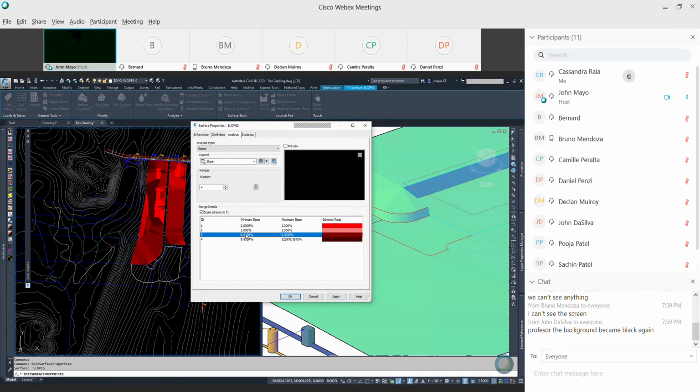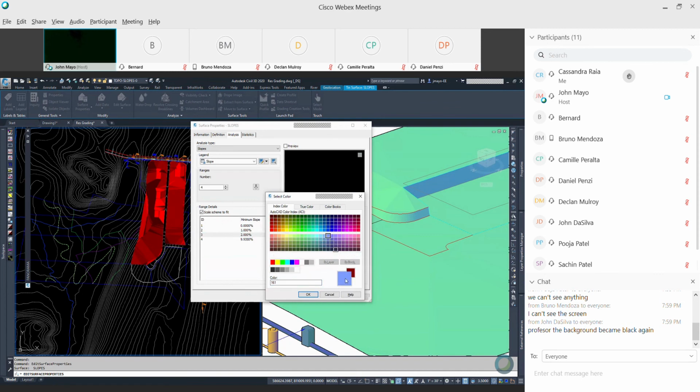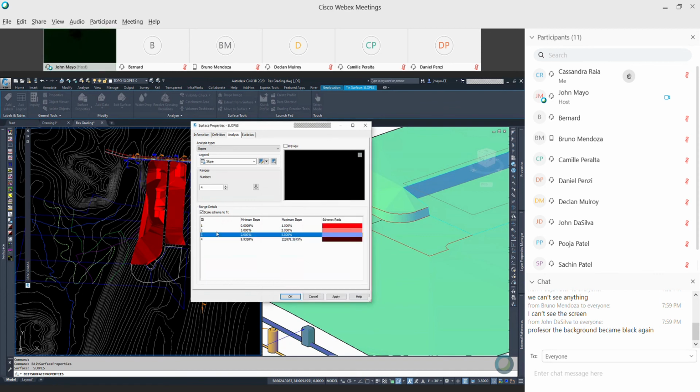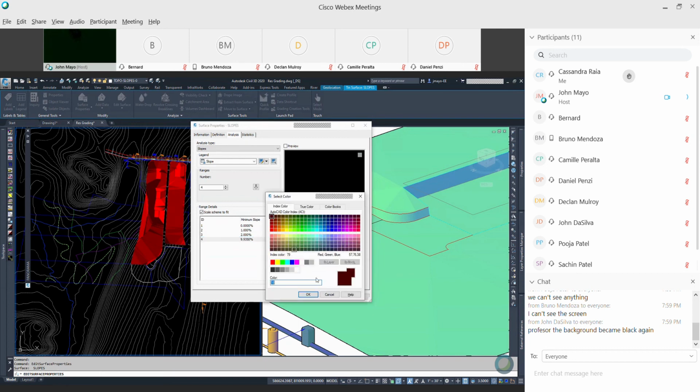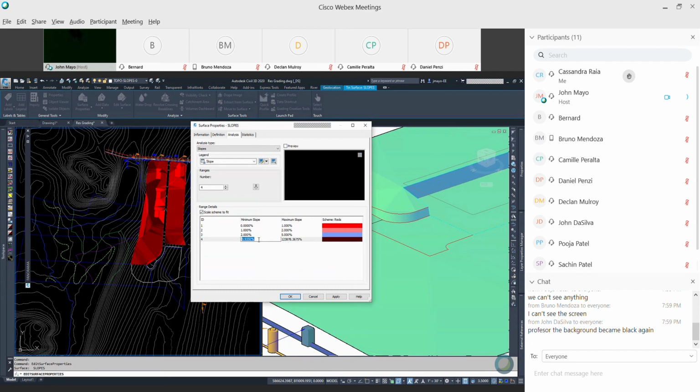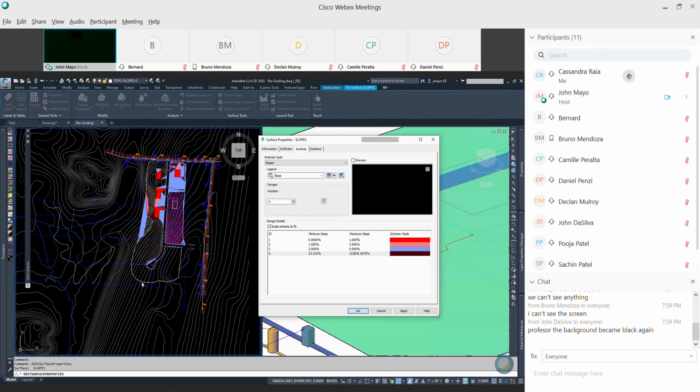And then this is going to show us now from 2 to 5, right? This would be acceptable parking. And let's make that green or blue. We'll see if we go over. And then I can show over here everything in real dark red anytime I go over 33.33%. I hit apply. I've got a scheme. So everything less than 1% is in red.